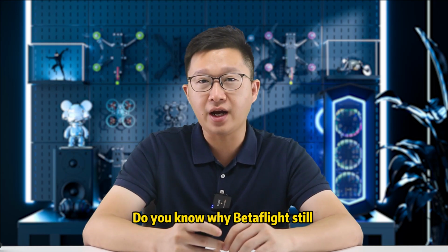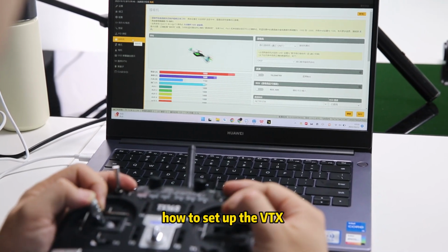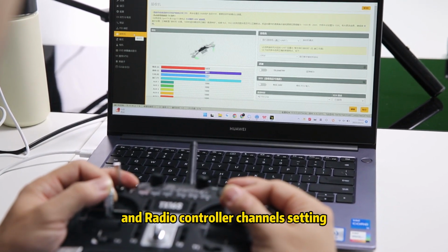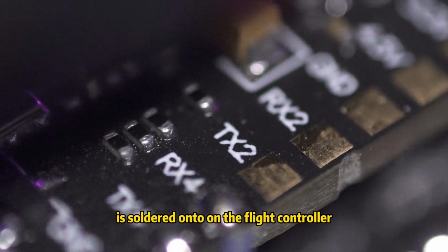Do you know why Betaflight doesn't display the FPV binding? Today we are going to talk about how to set up the VTX and the radio controller channels. Start by checking which port your receiver is soldered onto on the flight controller.